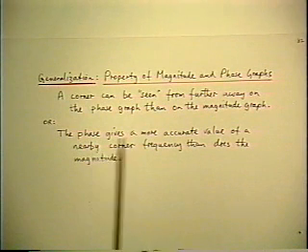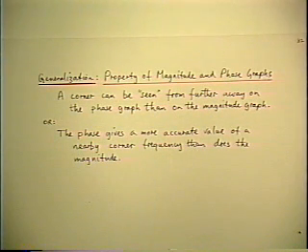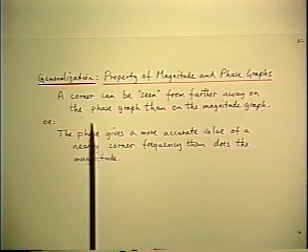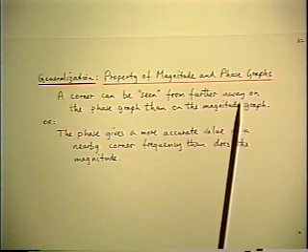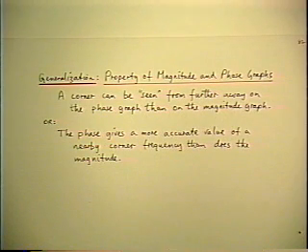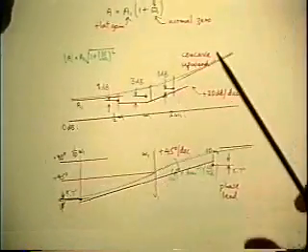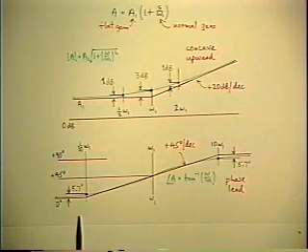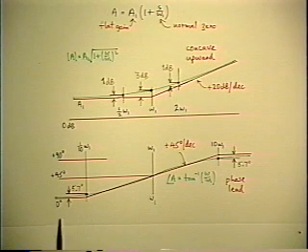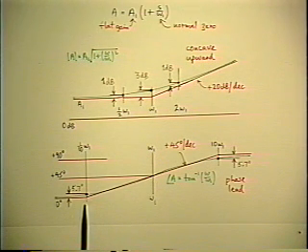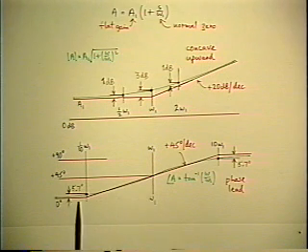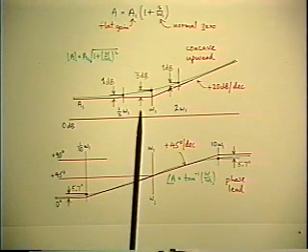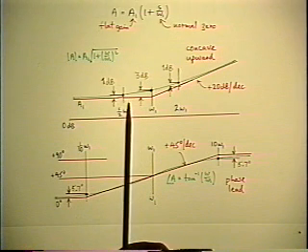Now you see why I made so much fuss about walking along the frequency axis and how far away from the corner the influence could be seen. The corner can be seen from further away on the phase graph than on the magnitude graph, because if you imagine yourself walking along the phase graph starting at 0 frequency, and you ask, when can you begin to see the corner? Obviously you begin to see it when the asymptote changes slope. But that's a whole decade below the corner, which is much further away than the octave on the magnitude graph.